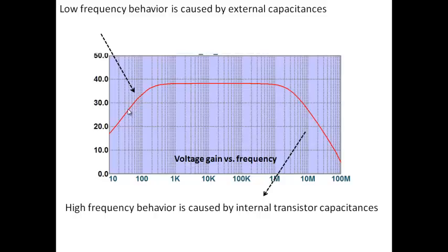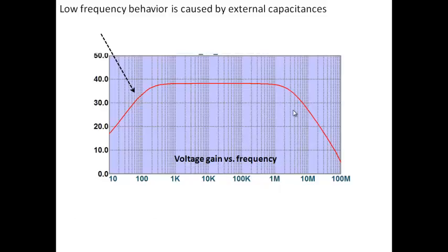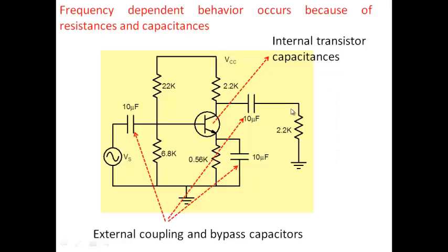The reason why one is lower and the other higher has to do with the magnitude of the capacitors. The capacitors that you see here are 10 microfarad, 10 microfarad, 10 microfarad. These are large capacitors. And you know that any cutoff frequency is 1 by 2 pi times some capacitor and resistor, so the 3 dB frequency is inversely proportional to capacitance.